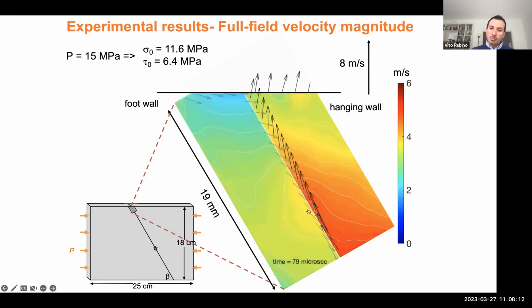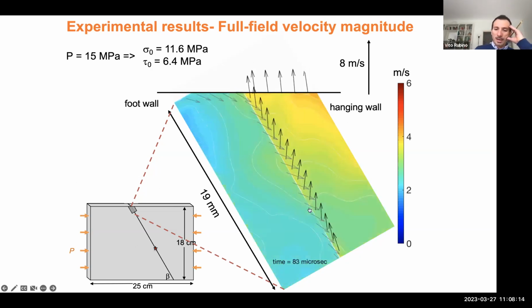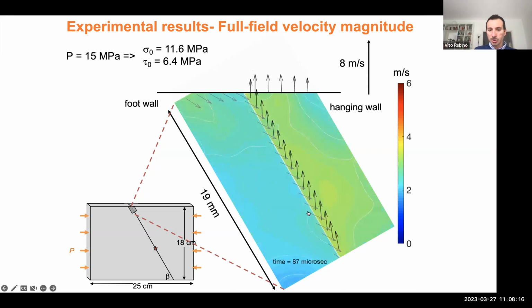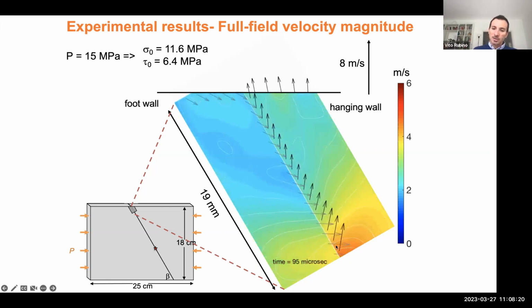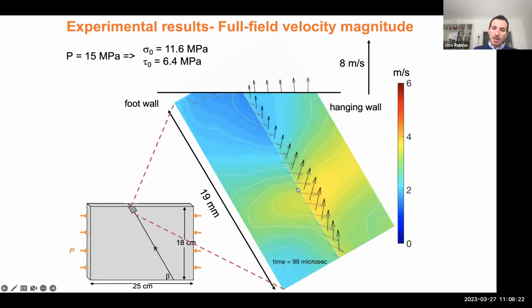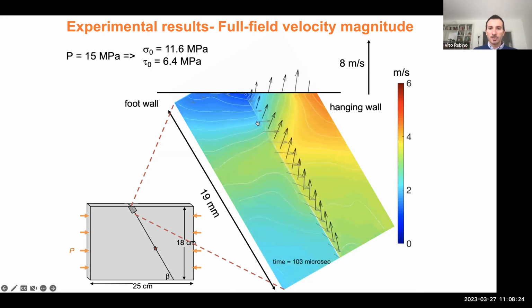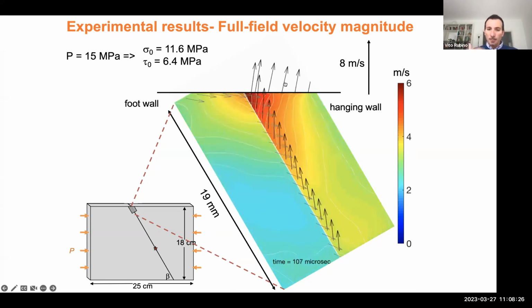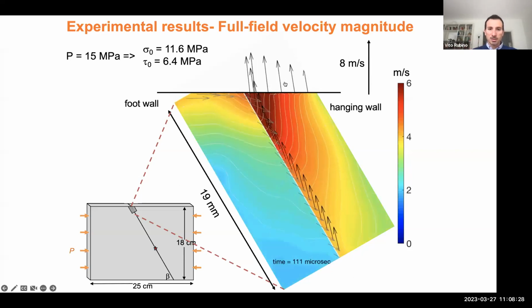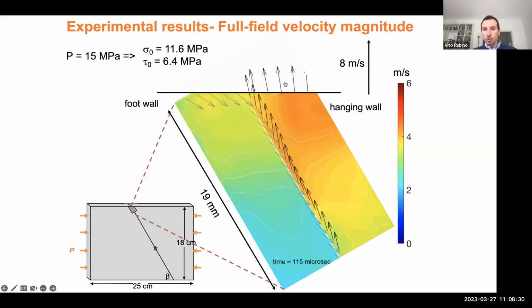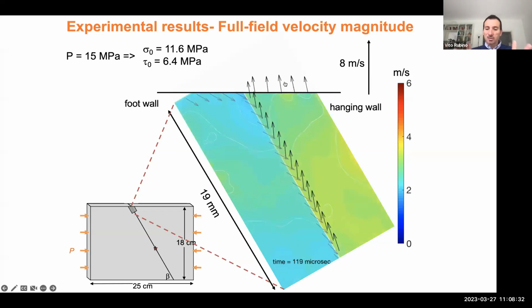It was a supershear rupture, and it is followed by a trailing Rayleigh rupture, which is coming in a moment. It's just coming here from the bottom, and it reaches the free surface. And these arrows indicate the particle velocity. It's amplified to show the motion. And again, this is purely an experimental measurement. There is no modeling at all.